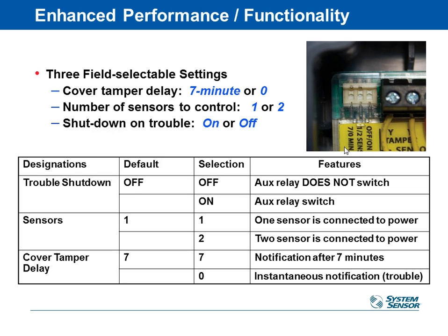There are a couple things that you can set on these. There are basically 3 dip switch settings that you can change. One of them is for the cover. If the cover does not close tightly on there, it will not close a little mechanical switch. We obviously want it to close tightly so that the sensing chamber can sense all the smoke. So if that cover is not on even or right or screwed all the way in, that switch won't make, and it'll make a trouble alert.